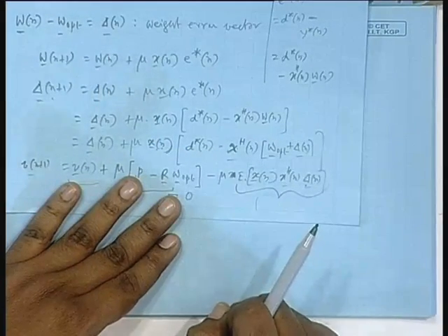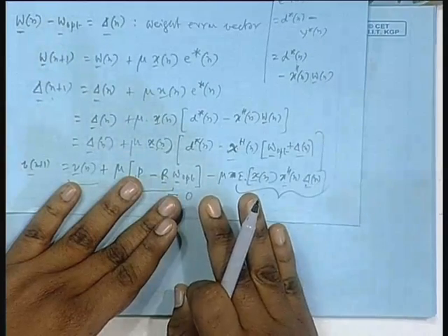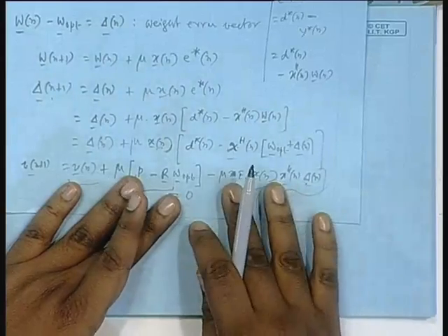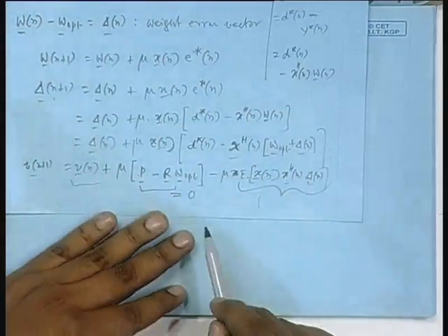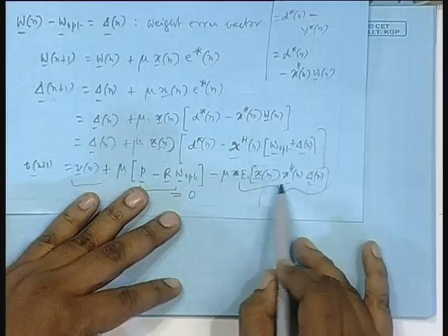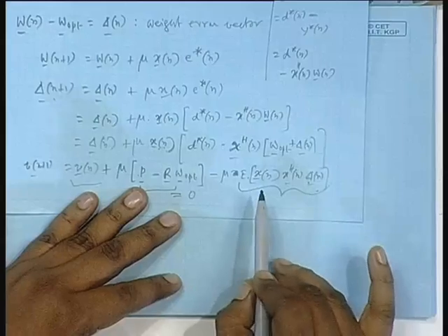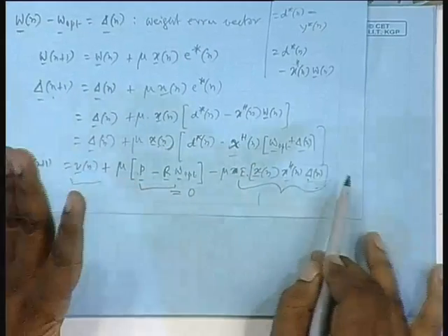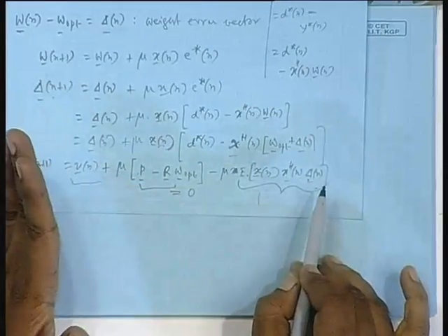So, under E there will be three terms. Are you following me? This is a matrix followed by a vector, evidently it will be a scalar, but the scalar component you can write as a summation of many small scalar terms. What will be a typical scalar term? A scalar term will be a product involving two data samples and one component of W under that E operator. Only if you have statistical independence valid, then you can separate them out. That is why you bring in statistical independence and not uncorrelatedness.